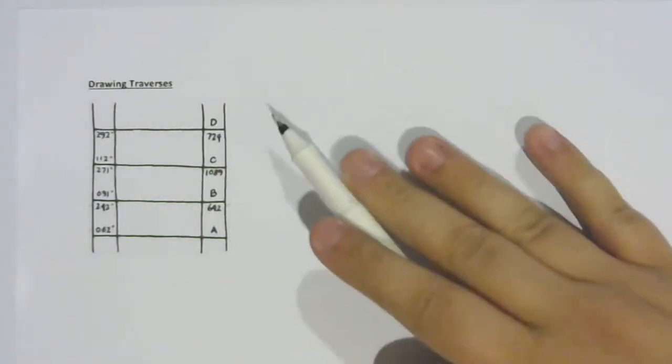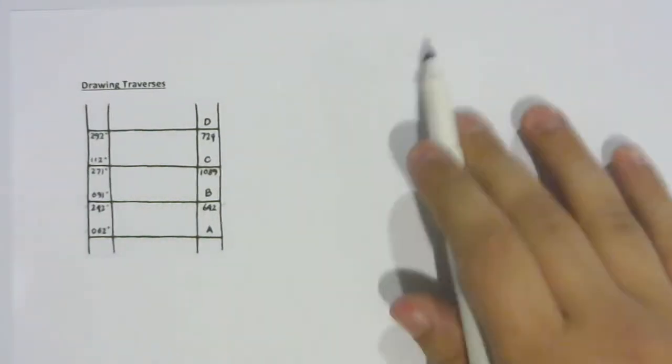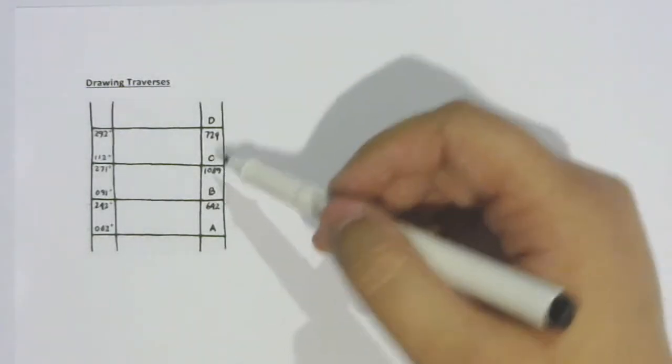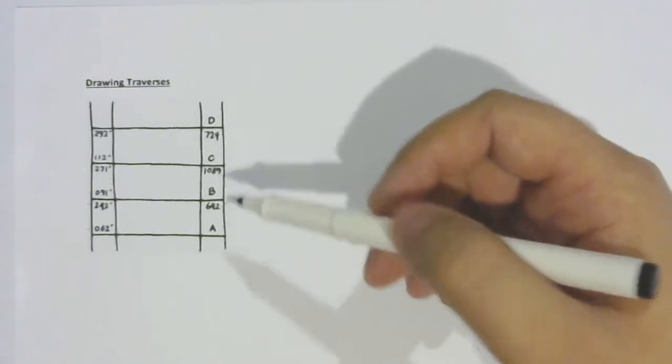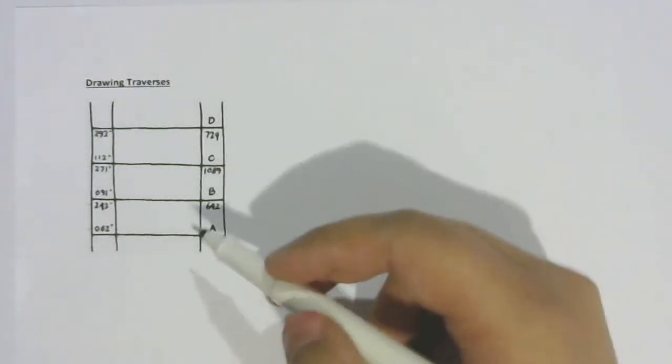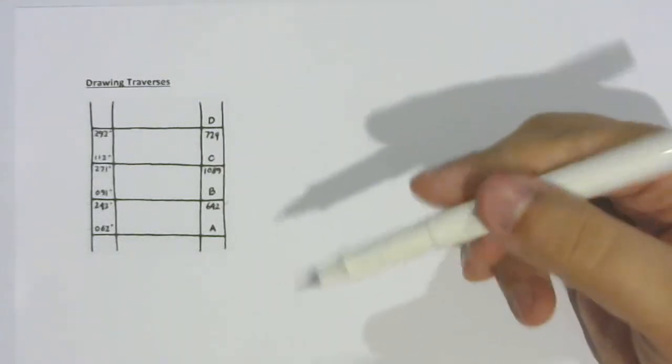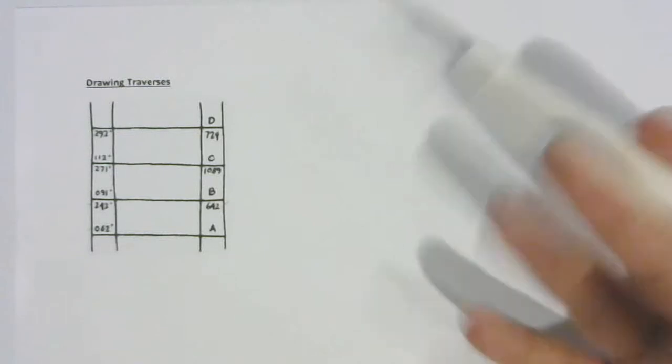So here we have what we call a traverse, which is simply multiple survey lines linked together. Now this is a simple one, we don't have any other information, so we're not actually doing any surveying to points, we're just surveying our traverses. And this might move around the edge of the property, it might move around the edge of a lake, it might move around the edge of a forest, something where just normal surveying doesn't help much, around the boundary of an object, essentially.